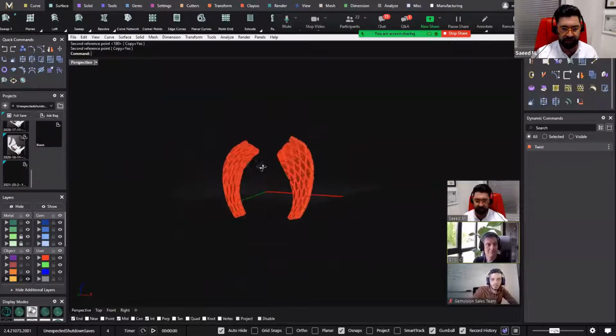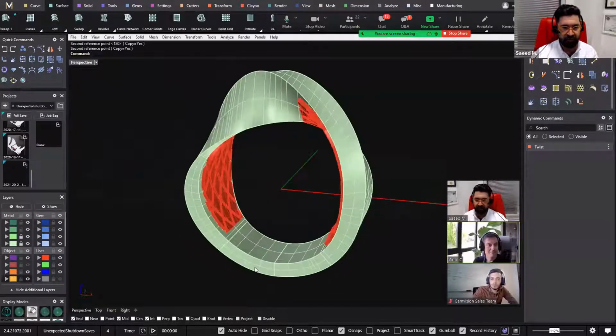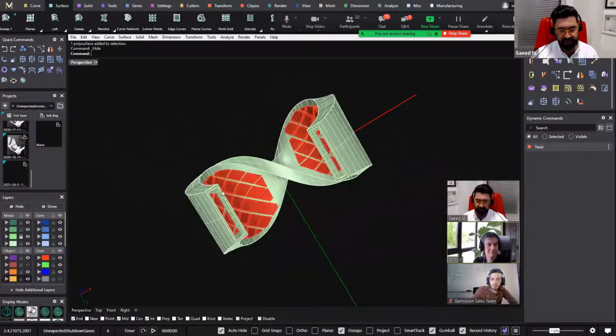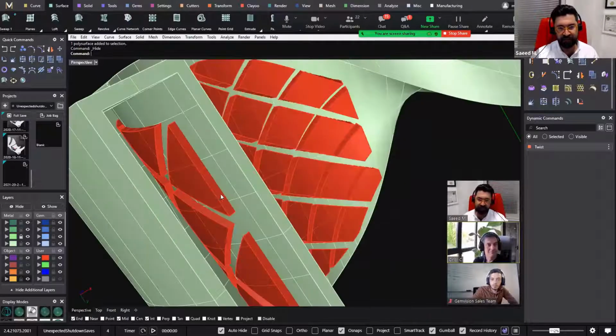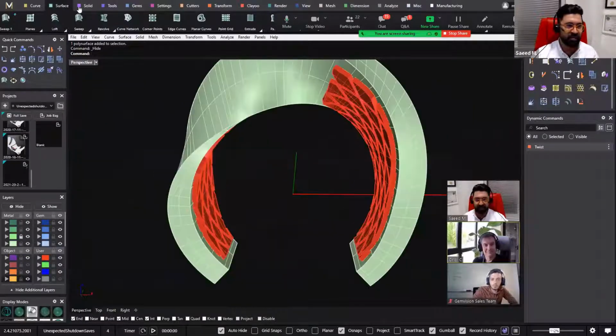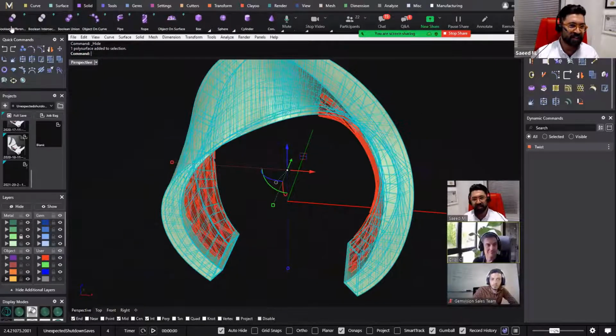And unlock it. You can see the 0.5 mm extra. You can see it here. Okay. And simply I go to the solid, and the Boolean difference is dynamic now. It's very funny and very nice.